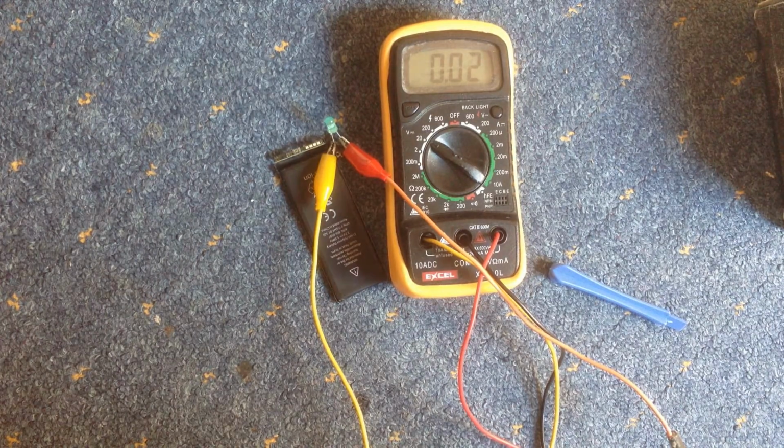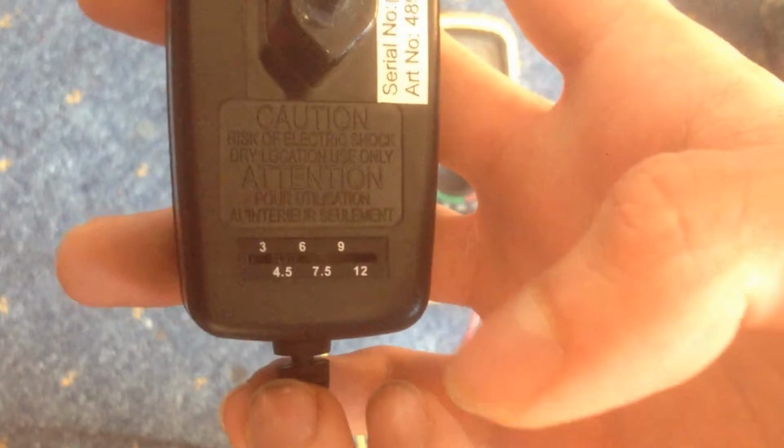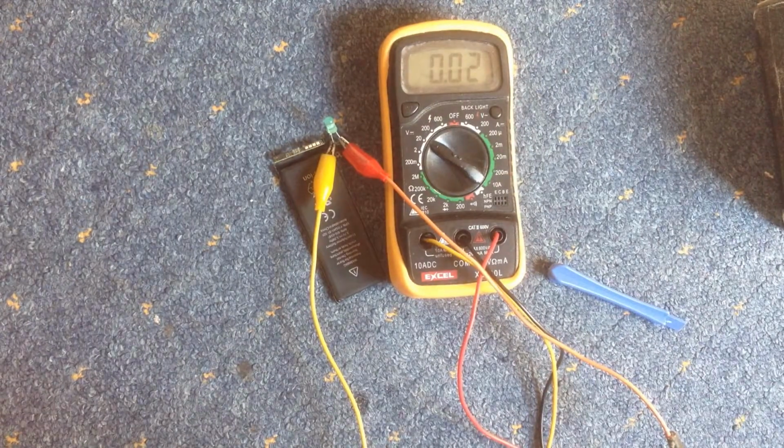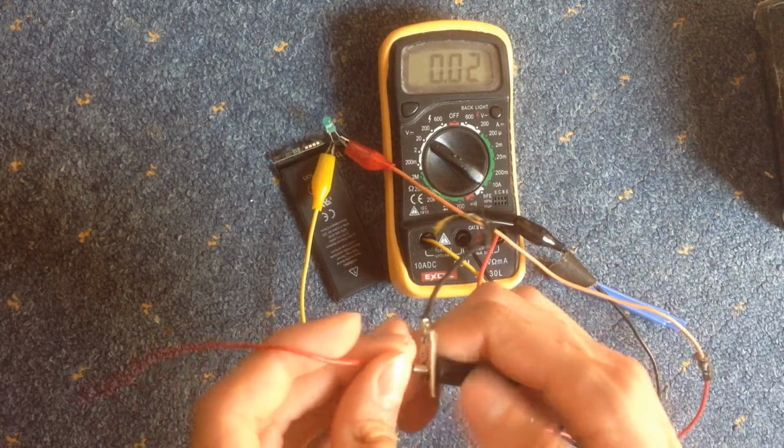So what we have to do is just manually charge it just a bit, and it's pretty easy. I actually recommend a bench supply to do this and just give it 4.2 volts. But you can just use such a cheap thing as this one as well, and just set it to 4.5 or 3 volts, something low like this. And let's just give it some voltage. You can use 5 volts from USB or a phone charger too if you want to do this. Let's just do it quickly.